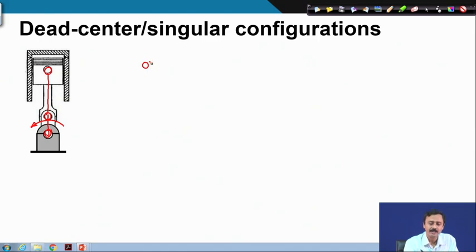come to momentary rest. So, at this instant, if I draw something like an equivalent kinematic chain, it looks like this. This is a 3R as it is seen here, but this has 1 degree of freedom exactly at this configuration, not if it moves out of this configuration even slightly.